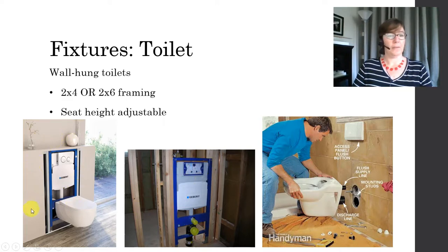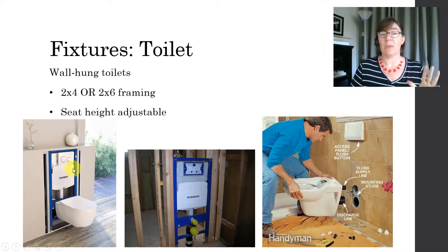All right, here is another one. It's kind of installed in the wall, but they haven't covered it yet. Okay. One thing you should notice is that you do need this space in the wall above the toilet. In general, this can't be a window right here, and you can't run any other pipes and utilities right through that tank space.